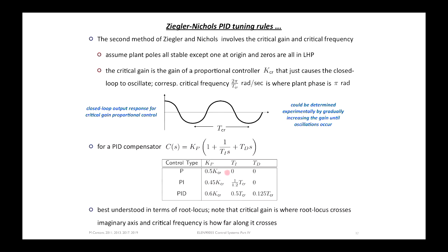So really the idea here is that you use a constant gain controller to push the closed loop to the edge of instability, where it just oscillates. If you think about the root locus, it's like drawing the root locus plot and choosing the value of k that puts the closed loop poles on the imaginary axis, and then you ease off. And you can see the easing off.